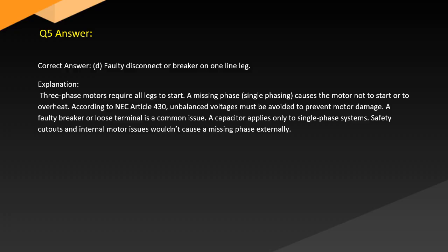A faulty breaker or loose terminal is a common issue. A capacitor applies only to single-phase systems. Safety cutouts and water issues wouldn't cause a missing phase externally.